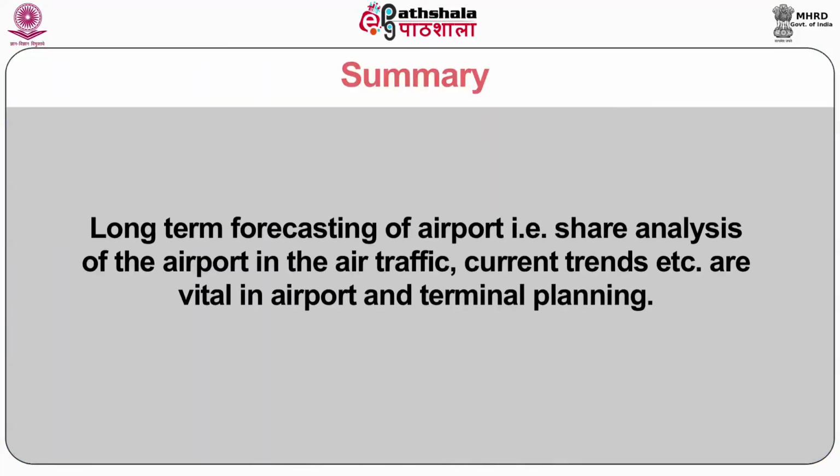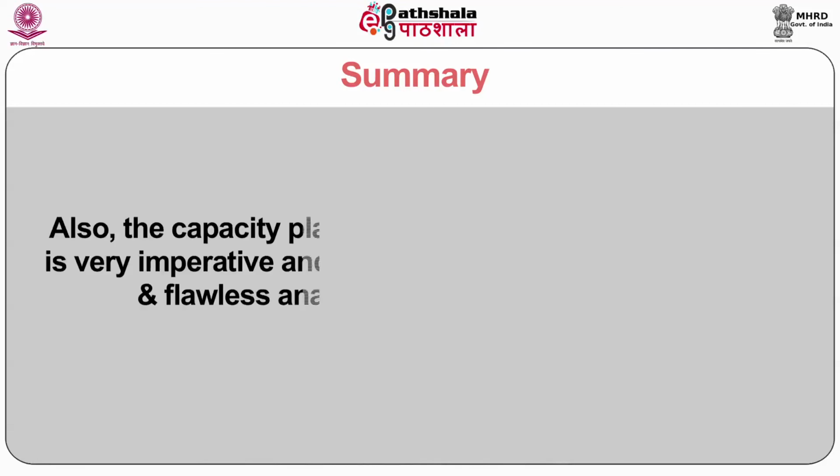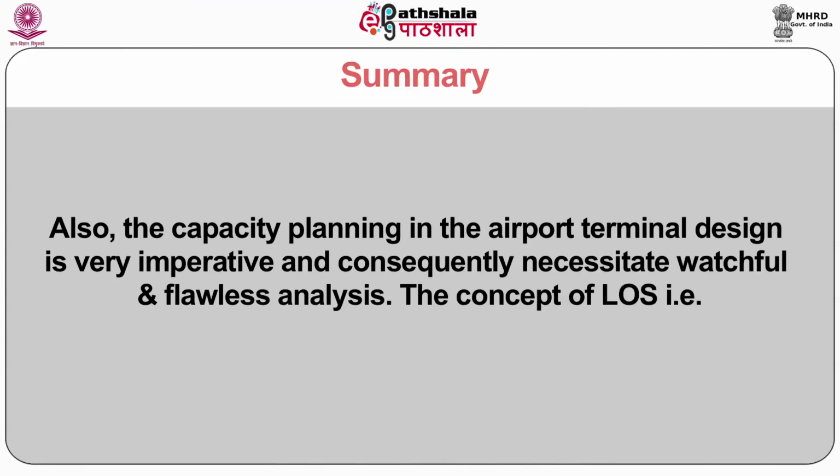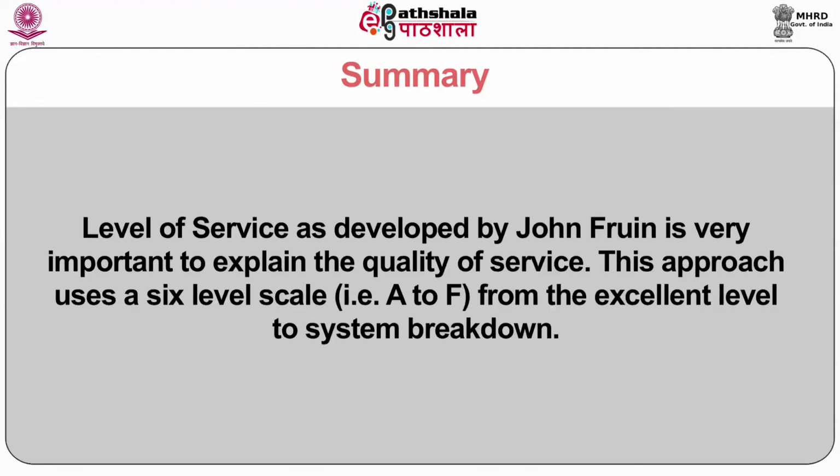Long-term forecasting of the airport, that is trend analysis of air traffic and current trends, is vital in airport and terminal planning. Also, capacity planning in airport terminal design is very imperative and consequently necessitates watchful and flawless analysis. The concept of LOS, that is level of service, as developed by John Fruin, is very important to explain the quality of service. This approach uses a six-level scale, that is A to F, from the excellent level to system breakdown.